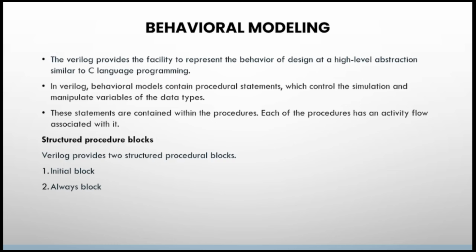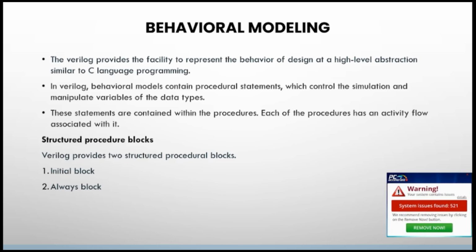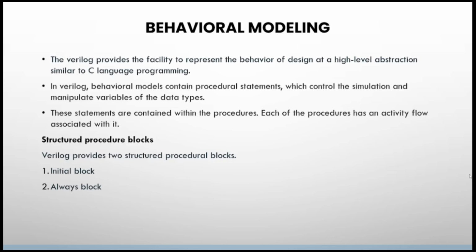Now coming to behavioral modeling. How are we going to write our code? Based on how your design behaves for particular inputs. So based on the behavior of your circuit, you will write the code in behavioral modeling. Gate level modeling is considered the lowest level of modeling in Verilog.